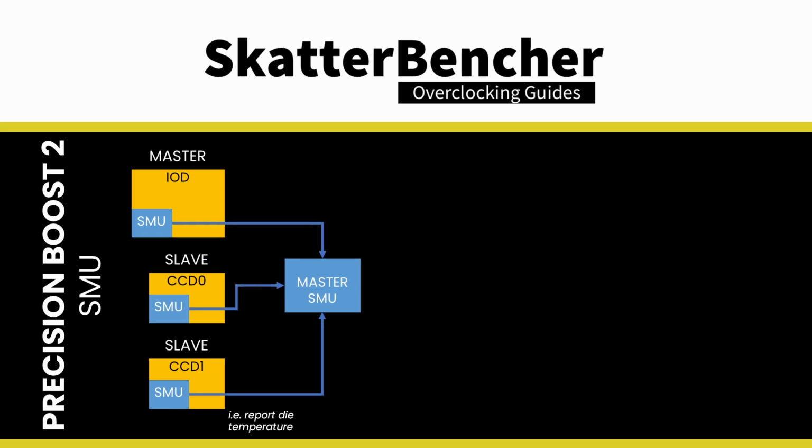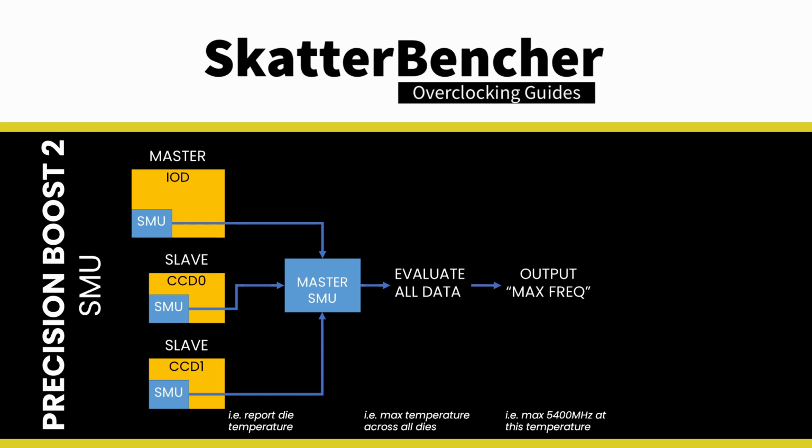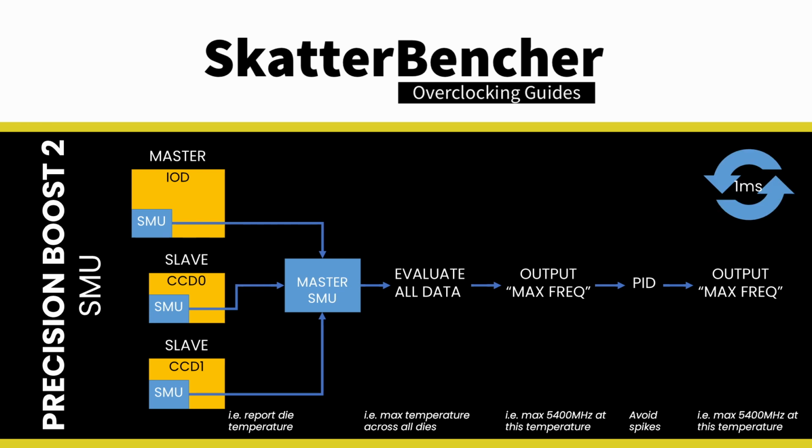First, receive the data from the slave SMUs, then aggregate the data into a single evaluation, with the output being the maximum frequency limit for a given infrastructure algorithm. Then input the results to a PID controller, which smoothens out the responses over a longer period and avoids spikes or quick changes. Lastly, the changing output of the PID controller is the maximum frequency allowed by a specific infrastructure limit at a given time. This process is repeated approximately every 1 millisecond for each algorithm.